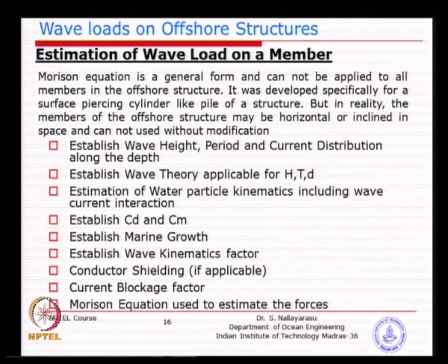We just simply go there and select a wave theory suitable to the site, and establish the water particle kinematics, basically your velocity and acceleration, which the wave equations can derive, whether it is Airy's wave theory or another wave theory. Establish CD and CM, which are definitely available nowadays, because you do not need to do the research yourself, they are already available in the literature or in the code books.